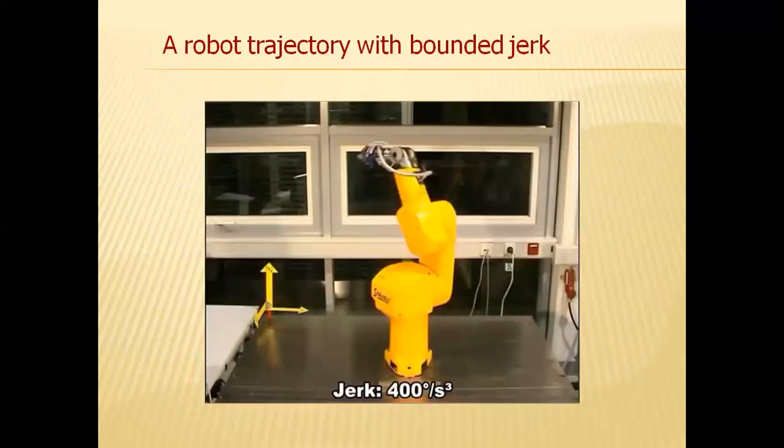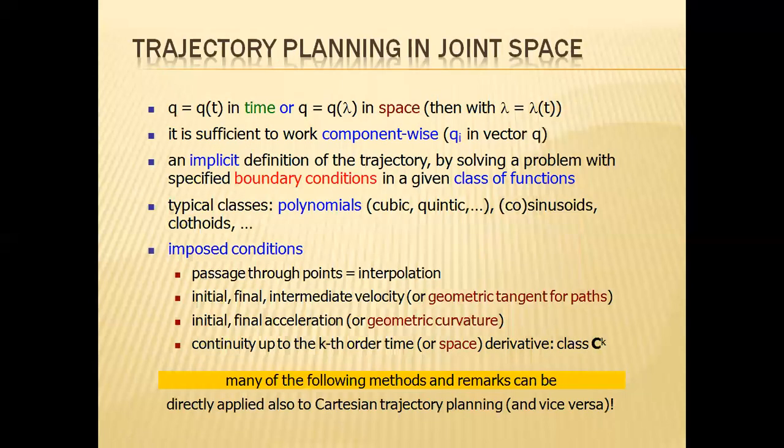So this is the symbolic representation working in three-space, that is, 3 degrees of freedom: X, Y, and Z. So the robot is allowed to operate in its work volume in 3 degrees of freedom. Sorry, three doubled, that is 6 degrees of freedom. Here that is positive X and negative X, positive Y and negative Y, positive Z and negative Z. So 6 degrees of freedom in the case of Cartesian space. So the nominal imposed conditions will be directed towards Cartesian trajectory planning.